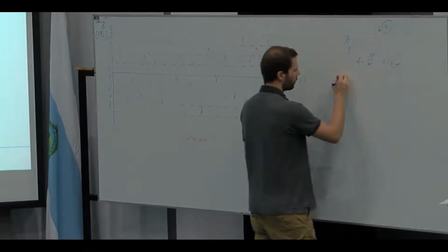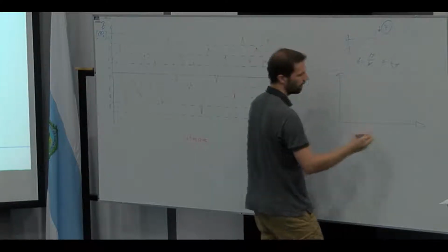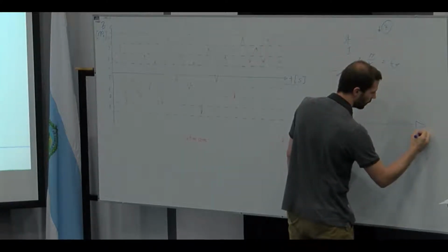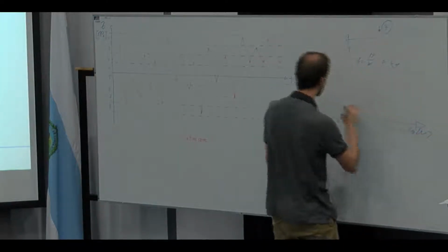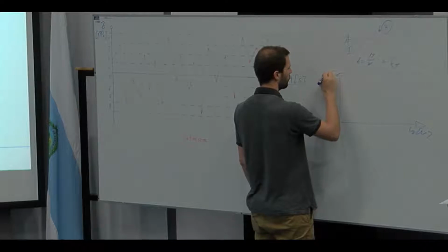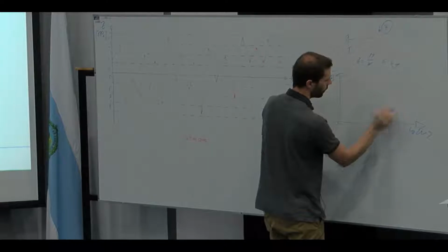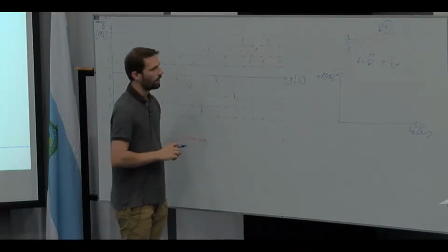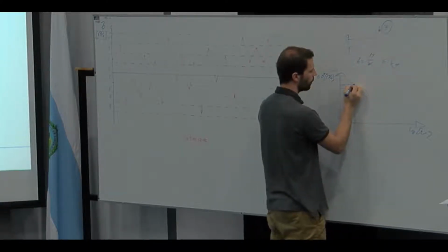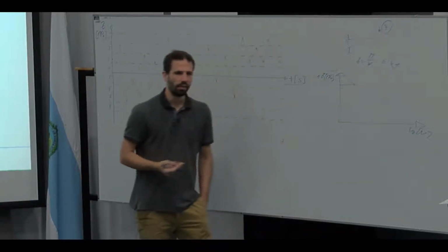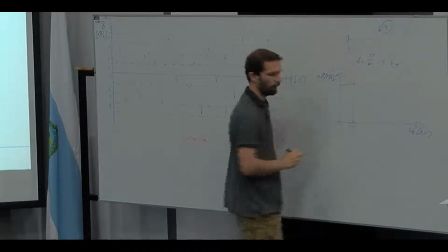If we now go for our fatigue analysis, we have here our cycles and here our resistance curve. If you always went with the highest peak, we would sum up here, and the amount of cycles we can take is really low.